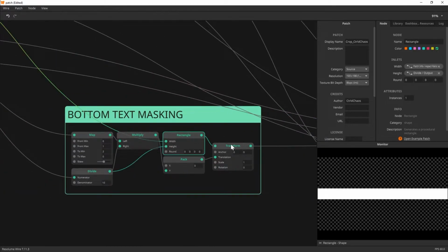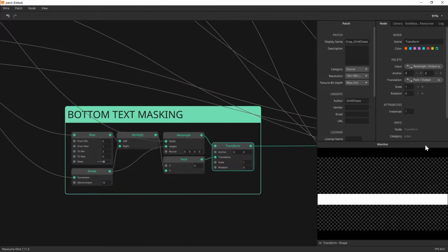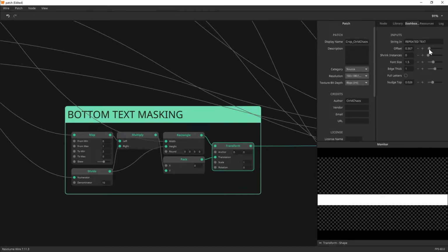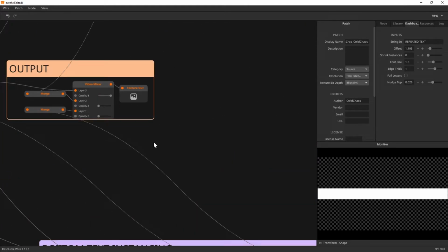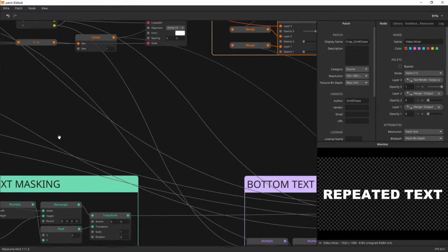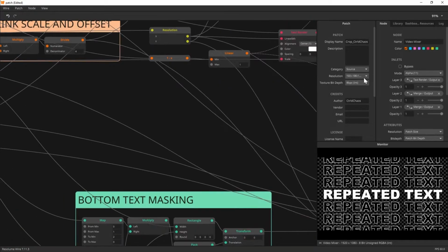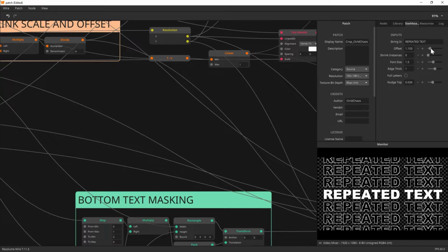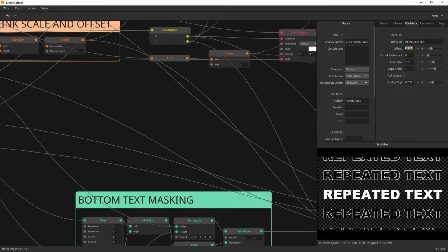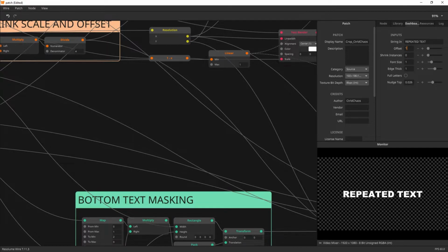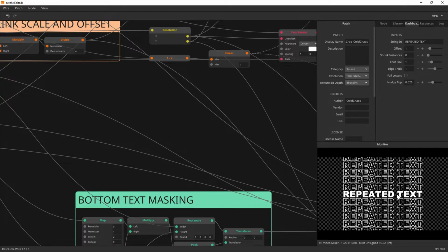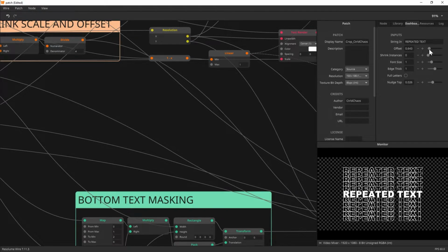So we want this rectangle not to be in the middle where it's fully there. We want it to move up and down. So when we're doing our offset, this is going to actually reveal different parts of the text. And the reason why it stops when it gets to 1, again, we made the value here when our instances are at 1 by 1. So when this is 1, and this is 1, they don't overlap anymore. When it's less than 1, they're overlapping.